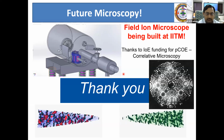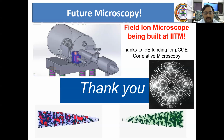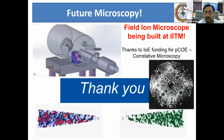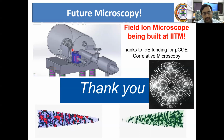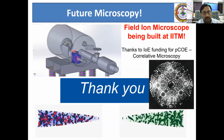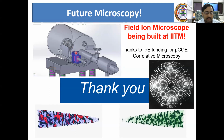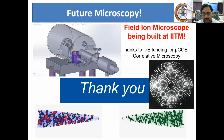In this microscope that we are building, since it's so customized, the stage we have, the blue one, is a cryogenic stage. On top of the stage, we are now trying to fit, let's say, a local tensile testing stage or indentation stage. That means we'll have the sample here. When we are imaging, at the same time, we'll be able to heat them and deform them. That means you push them, because once you get the image, you know the sample is still alive. So you can make a slow deformation at any given load and see the response of the deformation on the structure.